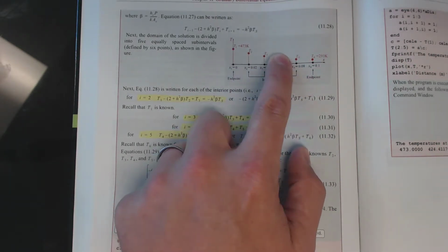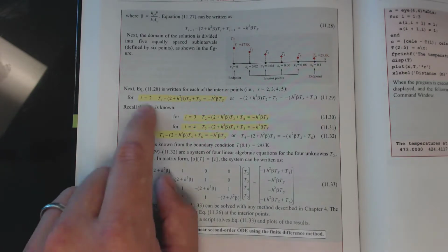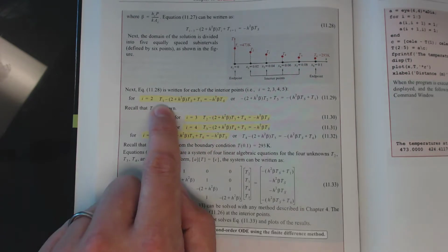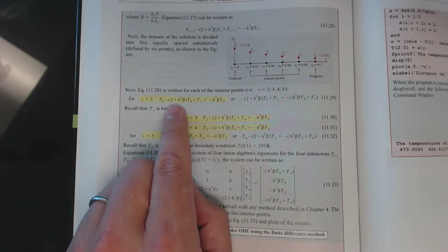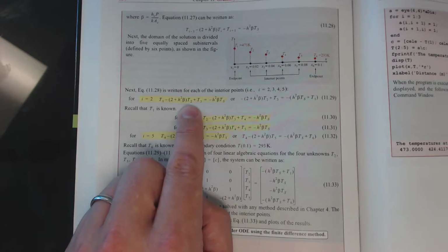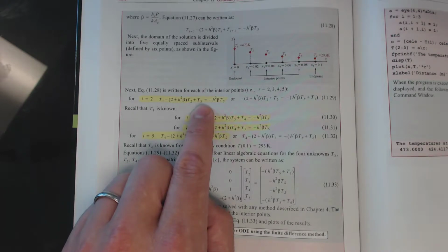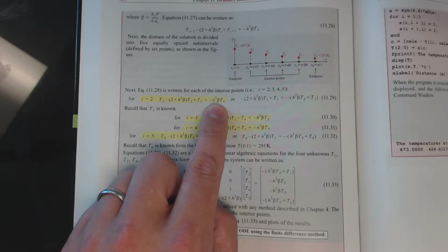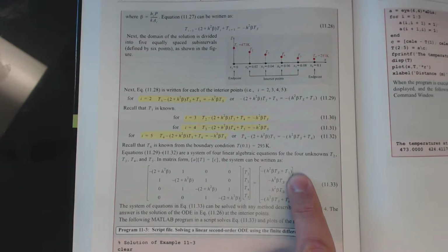So to get a reasonable idea of the curvature of this function, to get a shape of the temperature curve throughout, you just need to solve for the 4 unknowns in the 4 equations describing the interior points. You might guess that those highlighted equations below are exactly that. At point 2, you take the left-hand adjacent temperature, noticing that they've rearranged the differential equation so that each coefficient is associated right with its own variable. So there's the coefficient for T2, and the T3 coefficient is just 1. This all equals a set of constants, which could all be multiplied together to get rid of the alphabet soup there. And those constants essentially become the right-hand side solution vector of the matrix form.